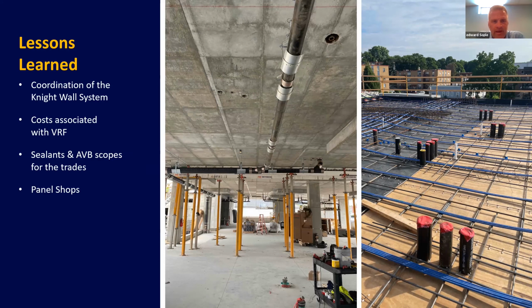What was interesting here, and I didn't note it here, is they dealt with the ERV system a little bit differently on this job to limit the amount of penetrations in the outside walls. We went to a central-based ERV system, and they also put the ERVs on each floor. Not every job will be able to do that. You have to give up square footage on each floor for little closets, but you also need to have access to the outside wall.